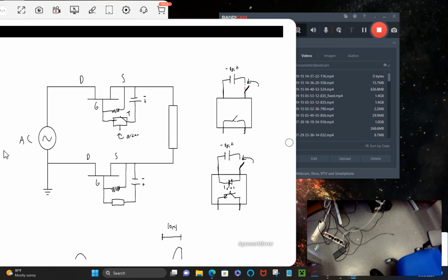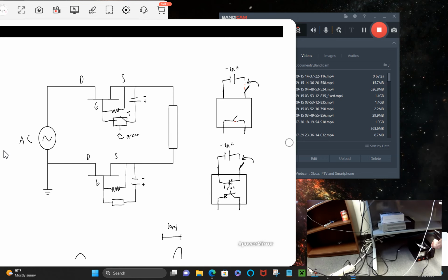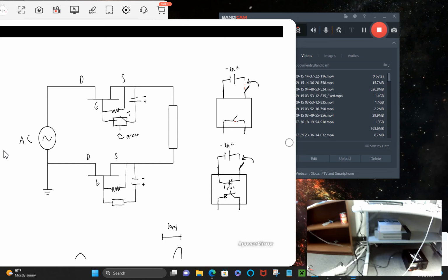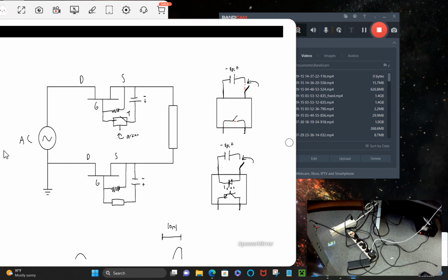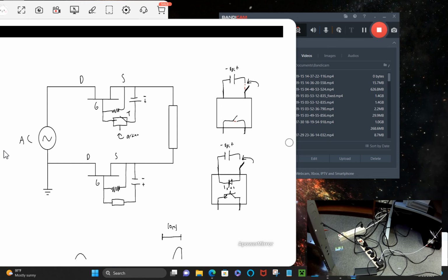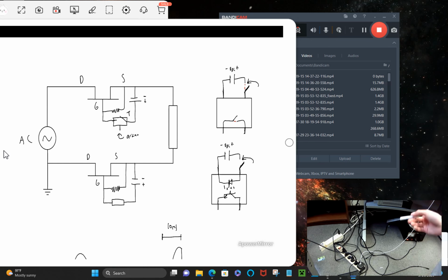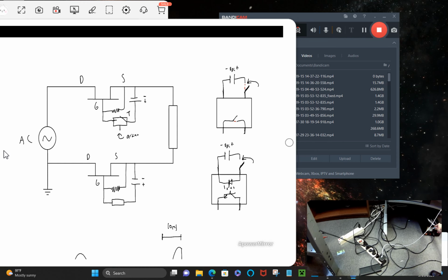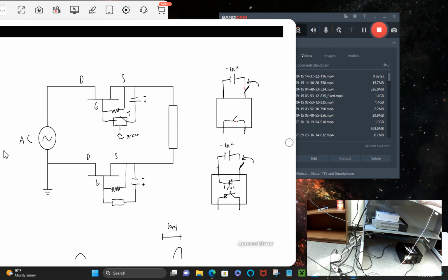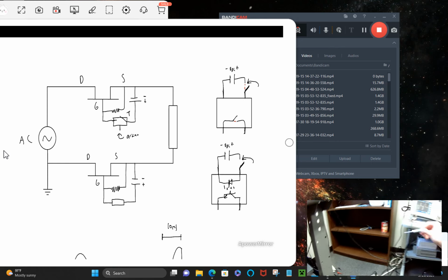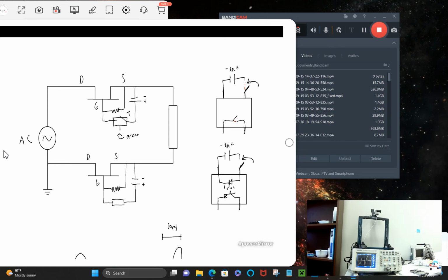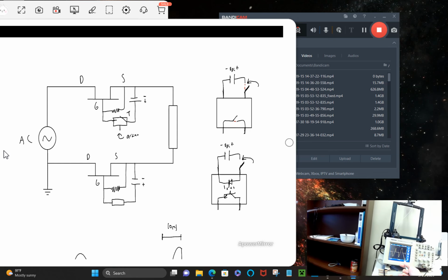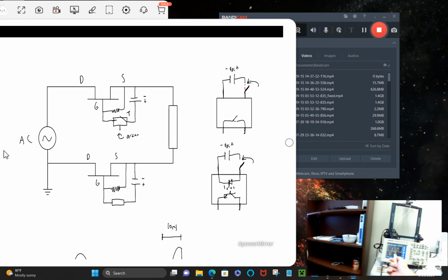And this machine down here, what it does is make our oscilloscope differential, such that it can measure the voltage across any 2 points, not with respect to an earth ground. In order to convert this to be differential, you need this machine. And this makes measuring a lot safer. So you plug this machine in, and then you plug it into supply power to the oscilloscope. And now this oscilloscope is completely floating such that it's differential and there's no hazard when you measure.